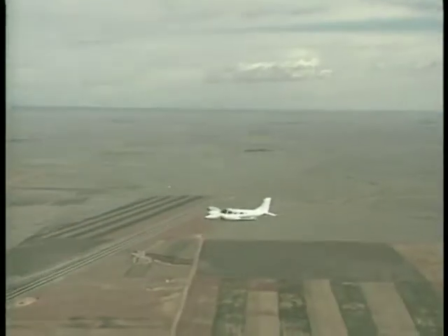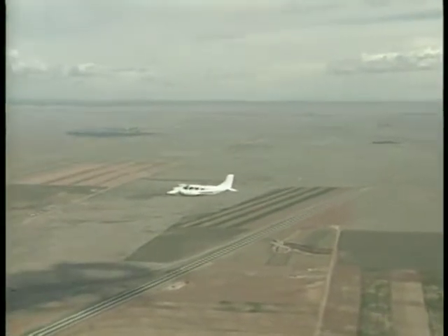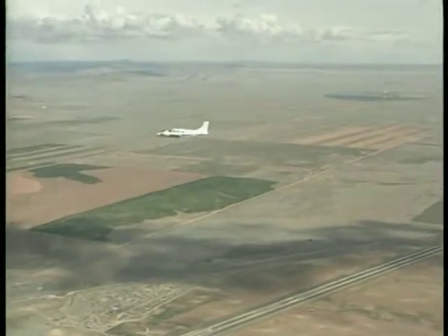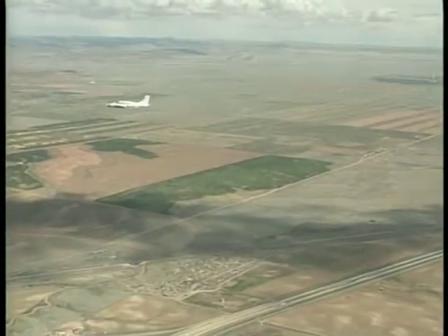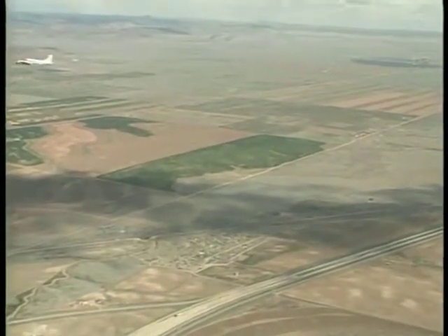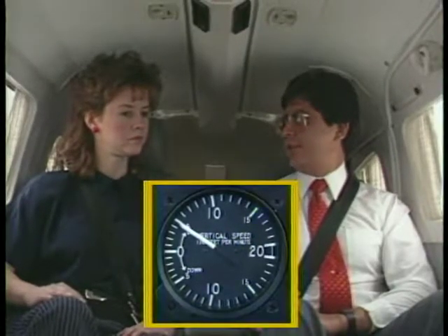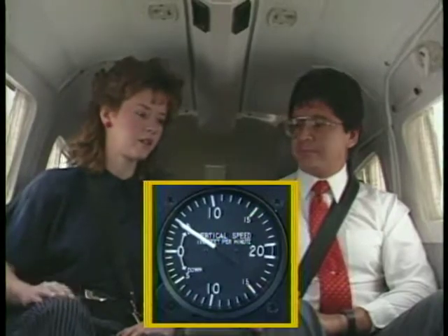During the climb to your en route altitude, you may want to transition to a cruise climb. The higher airspeed reduces the time en route, improves engine cooling, and offers better forward visibility. The lower climb rate is more comfortable for passengers, especially in a non-pressurized airplane.